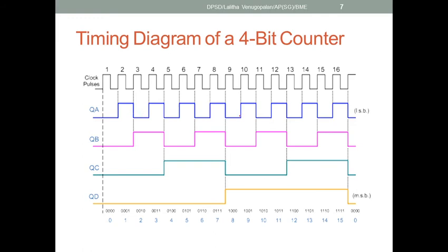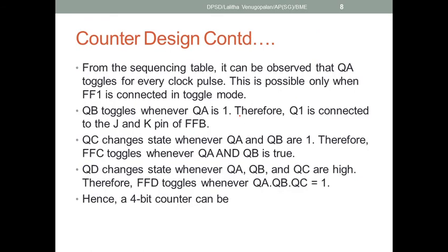However, like I said, your flip-flops are memory elements. They are also made up of gates, and then you'll have additional logic circuitry which is also used to construct a counter. So overall there will be a small propagation delay. It's not a circuit without any delay at all. However, when you compare it with an asynchronous circuit, the propagation delay is not that significant and they are quite fast. So if you see the circuit diagram, this is what I have explained, right?